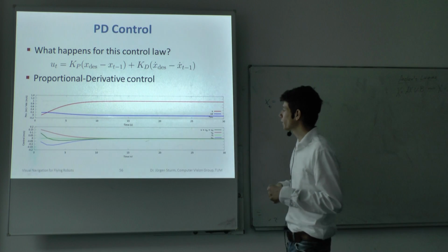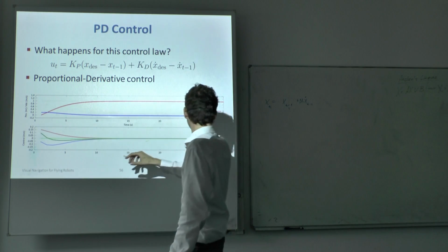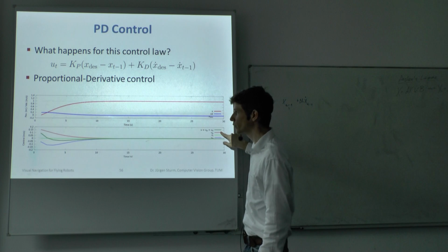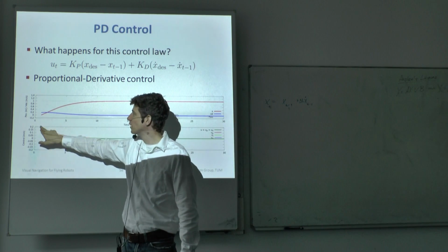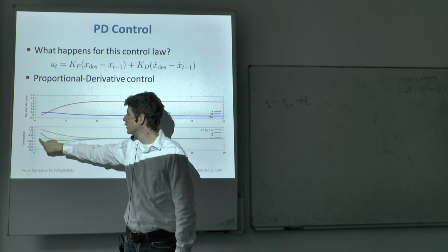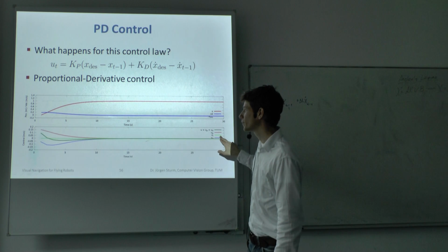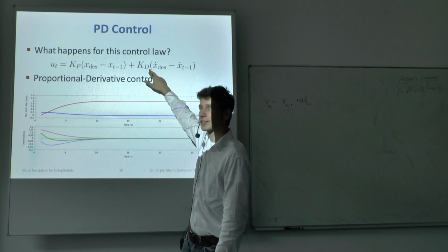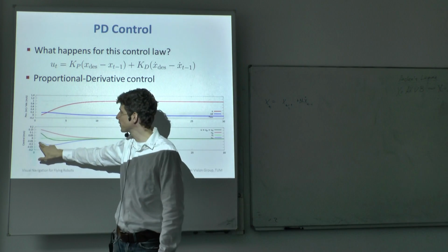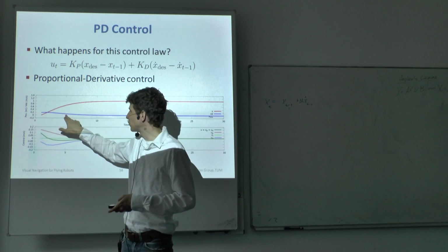And when we now look at the individual contributions of these two components, then you see that the proportional part is the red part. So the proportional part says we need to accelerate in this direction, and the blue part is this part here that controls the velocity, and this part tells us that we have to reduce the velocity, so that we actually achieve 0.